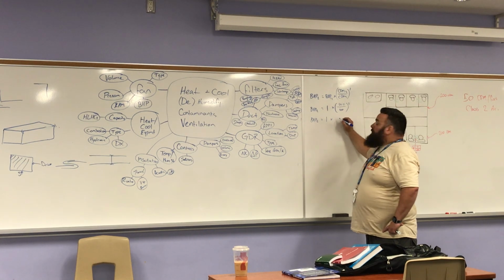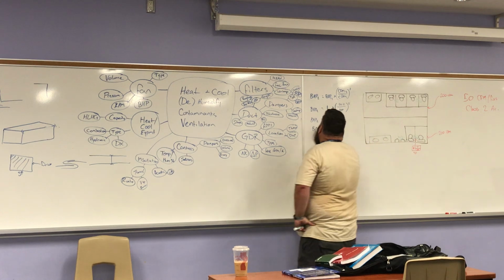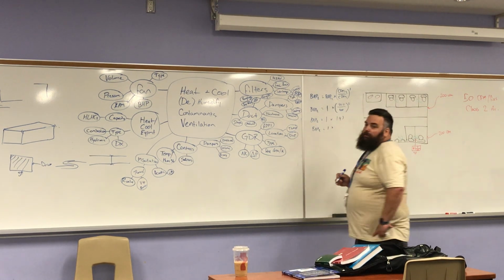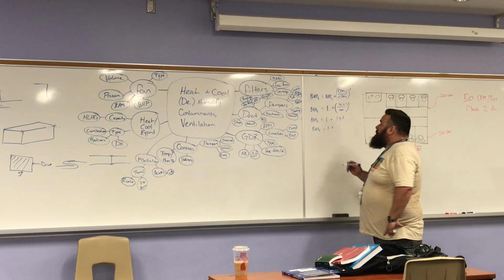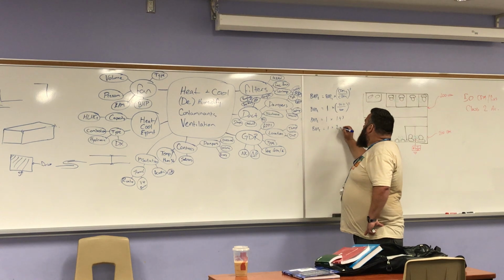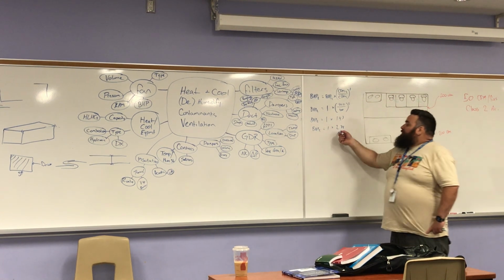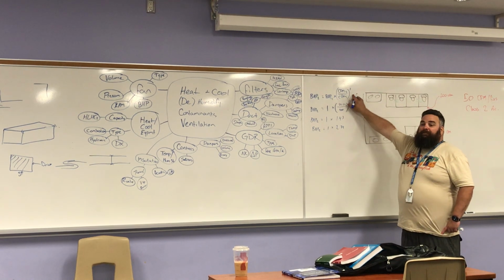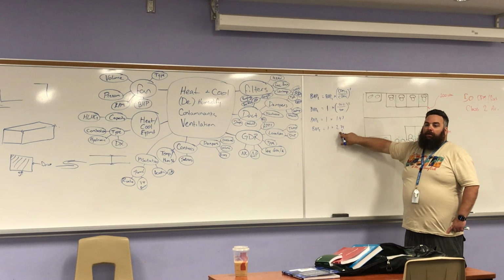Sorry? 1.4 cubed. What's 1.4 cubed? 2.7, round. 2.7? Yeah, well, 2.744, but okay, 2.74, let's do that. So, I increased my CFM by 180 CFM, and it increased my brake horsepower by 274%.